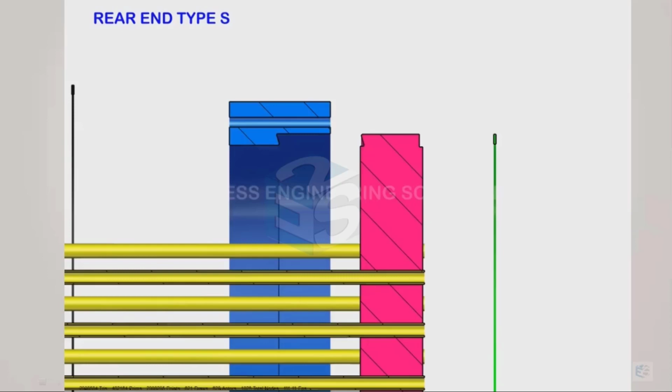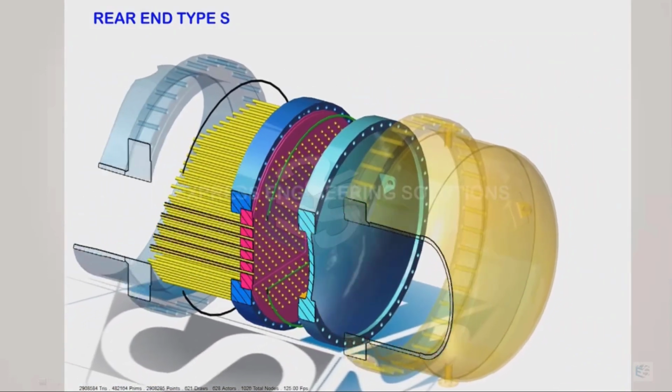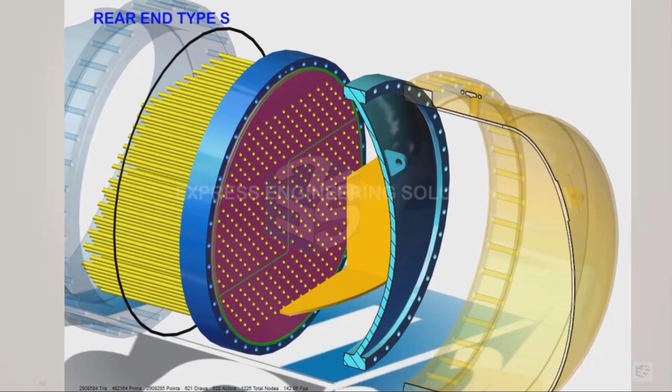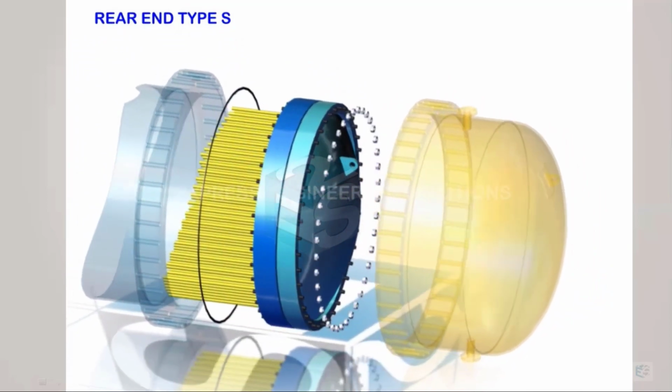Since it has a lesser diameter, it has to be made in two halves, and the two halves will come and engage with this arrangement provided over here on the tube sheet. It is going to get fixed. So this split ring is fixed with the tube sheet. Here comes the gasket which is going to fit over here. So now we can have a look. The gasket will come and sit over there like this. This is the floating head along with the pass partition plate. That is going to be placed over here, and then the bolting will happen for that floating head.